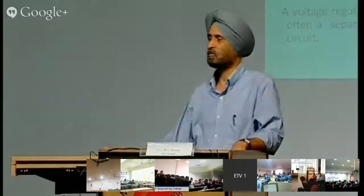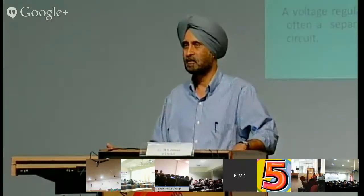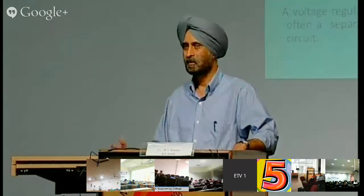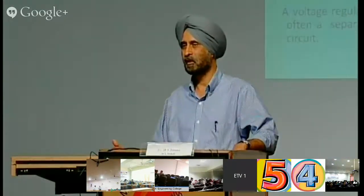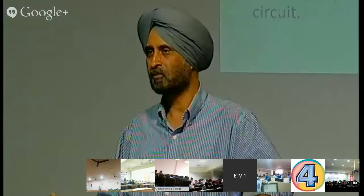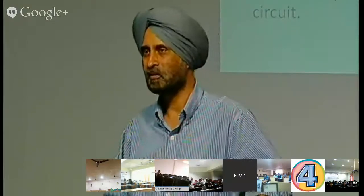One very good example of voltage regulators commonly used in our houses is with the air conditioners. There is a voltage stabilizer, as it is commonly known. It also does voltage regulation. It takes the 220 volt supply and gives an output of a fixed 220 volts. If the input supply goes to, say, 240 or 250, the output is still maintained at 220 volts only. This is the concept of the voltage regulator.